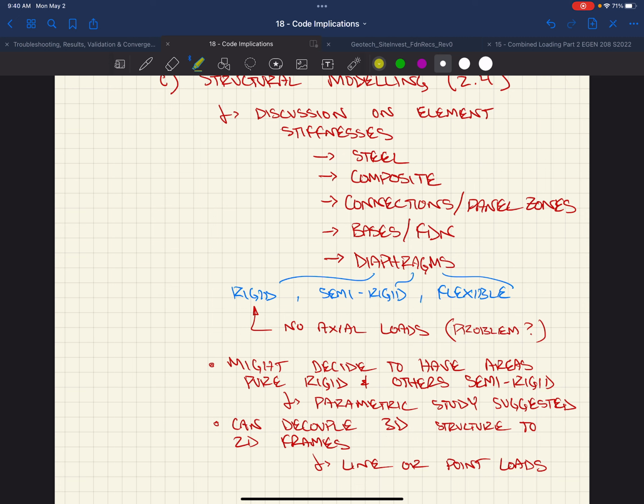So if you have this model that's a moment frame, so this is a moment frame beam, you have reverse curvature in this beam as you're pushing on this building. You're going to have stiffness that's added based on the fact that you have parts of this beam that are in positive bending and you got this in concrete and compression. And then you have areas where it's not contributing. How do you model that?